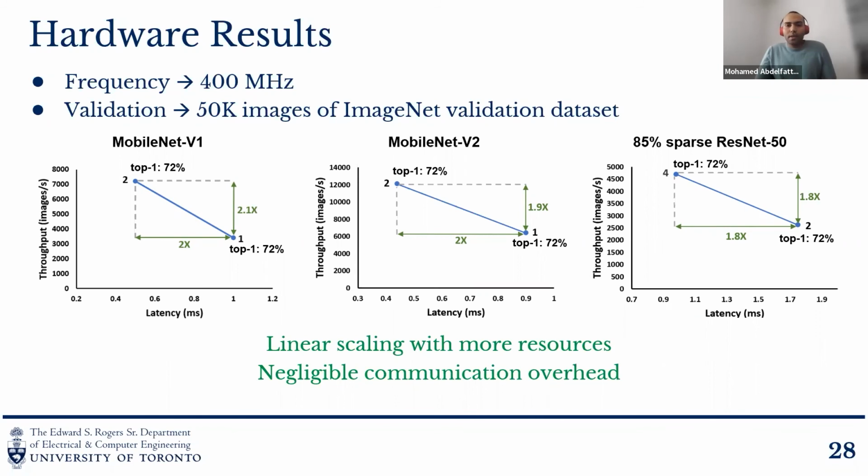the 100 gigabit Ethernet that we're using and the fast Pegasus modules that abstract away all Ethernet related operations and allow us to just compute our computations in a fast manner, just as if we're having a single giant FPGA with just FIFO interfaces between the boundaries.